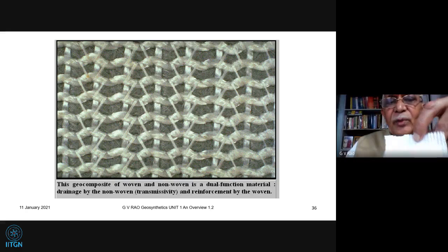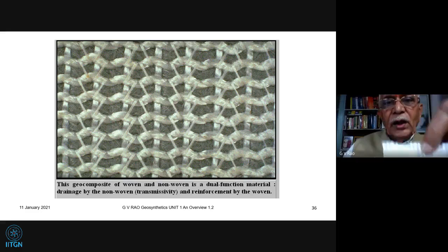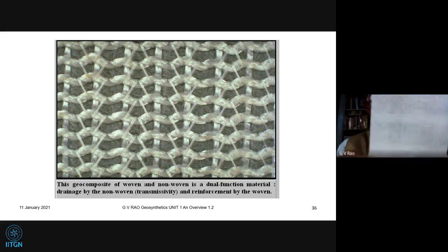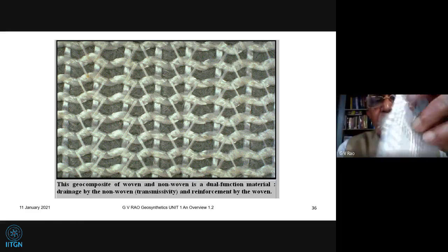Now some people in presentations assume that knitting is something like a sweater or a banyan or socks. No. Here, the yarns actually are coupled with the non-woven geotextile by using a knitting system. So that is why on the right side, if you see, I don't know if it's very clear or not now, but we can see up and down, there's a basic thread which is going to knit these yarns in position.